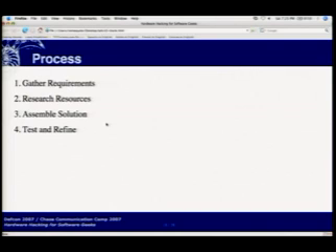Requirements also include things like low cost, maybe easy to assemble, and able to be built in a home lab. But they're also the functional requirements of your device. Like this one, the requirements are user programmable, moddable, and display text on a bunch of LEDs. So it does all that. But generally this process is iterative. If you see a board that's got rev and then a number after it, that's how many times they've done a different release of that board. Usually companies start with special revision numbers so they don't have to tell anyone how many revs they went through before it worked.